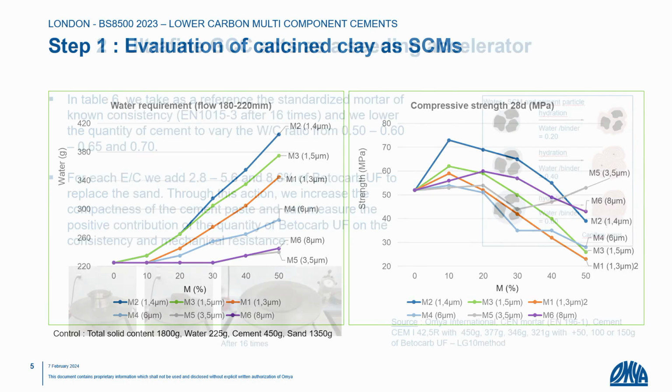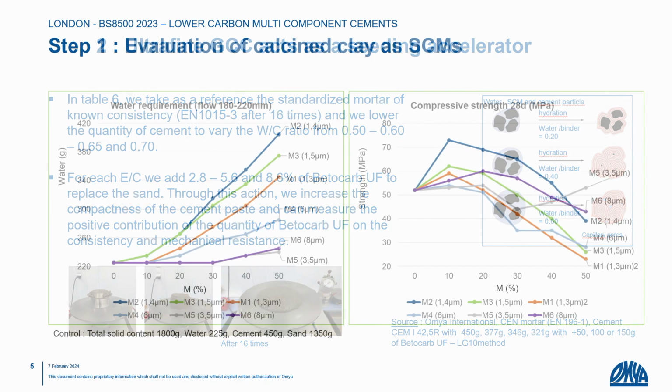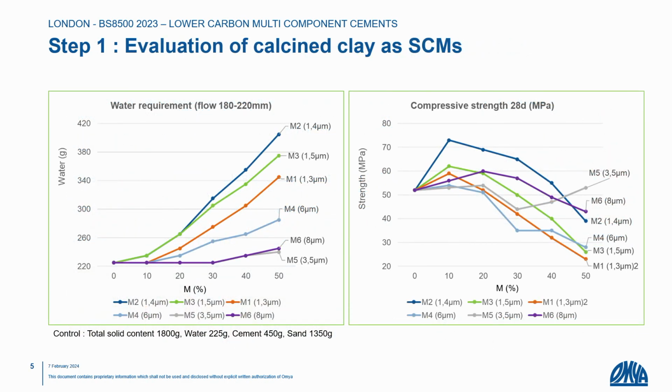The second model formulation, of course, when I speak about this point, just to remember, this is exactly more or less what we do with the activity index. This is just an extension of the activity index, but we have here the advantage of the variation of the proportion of the mineral addition and the first information on the water sensitivity of these mineral additions.